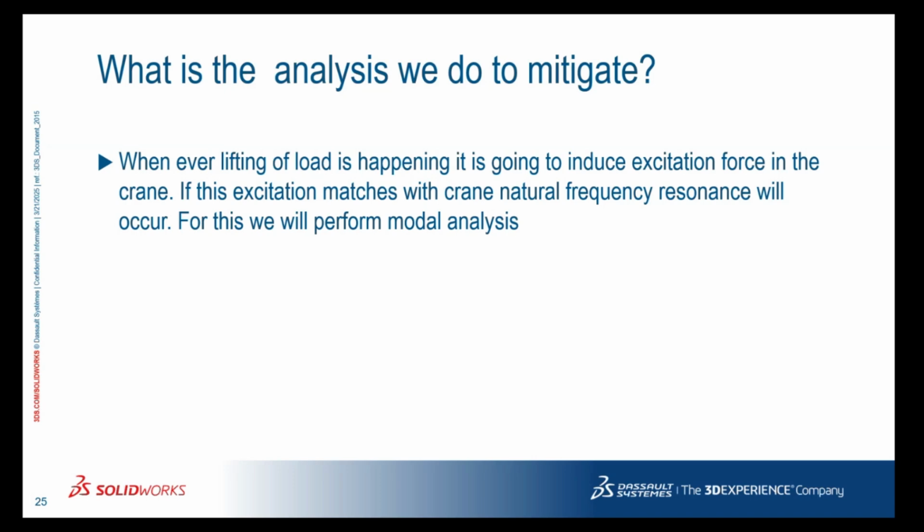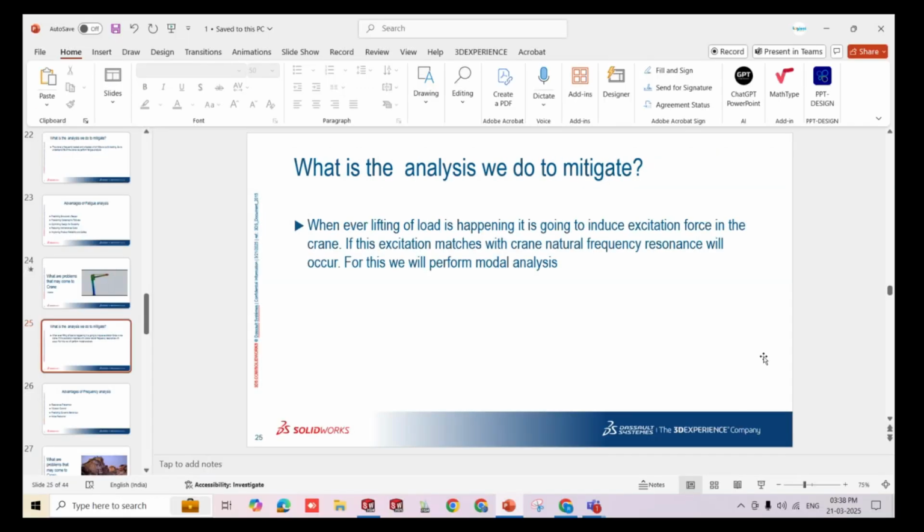Also, due to swaying, there may be some excitation force which will be transferred to the crane, and if this excitation matches the natural frequency of the crane, resonance is going to happen, and we don't want resonance to happen. If resonance happens, then the crane is going to vibrate in a higher fashion, which is not desirable.